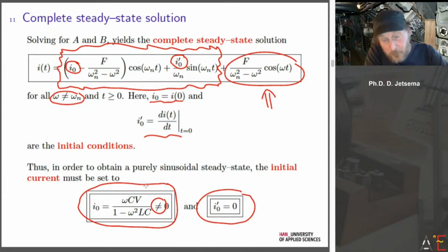So all the computations you see in all these papers on power factor improvement using lossless LC filters, and the same holds for a more complex filter, where the equation becomes a lot more involved and you have many different resonance frequencies, so for each resonant combination of LC elements you need to set their individual initial conditions.